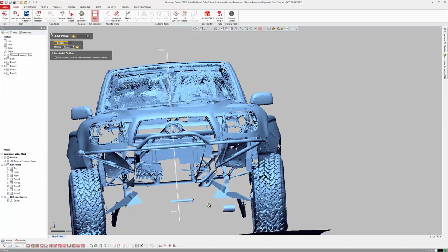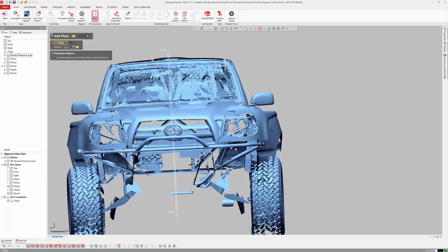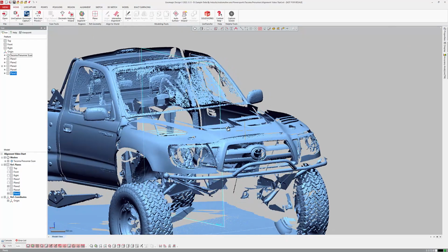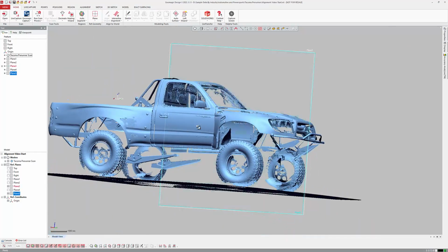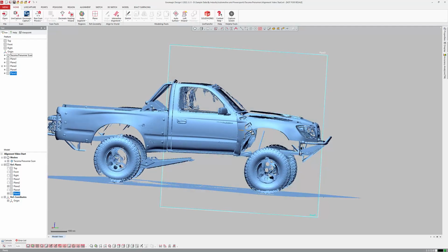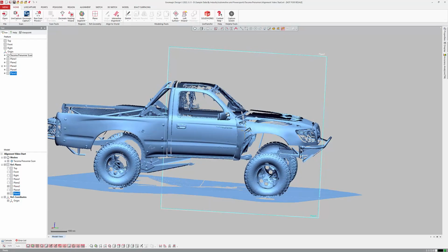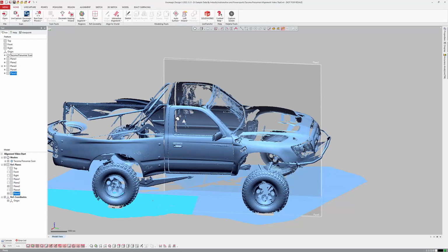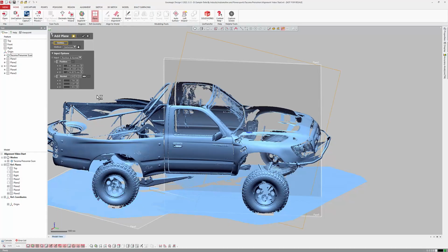Using the trailing arms there. So there's two different methods to find a center line plane of the vehicle. Now, for basically the Z here, obviously, we could use that same extract method to select the floor, for example, and that could create just another best fit plane using that data, and that could be a secondary datum.